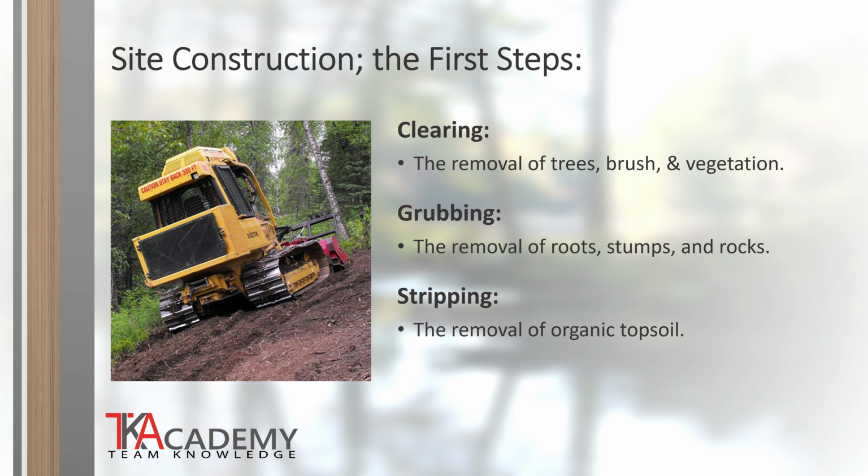The topsoil is where the nutrients are that plants need to thrive, and this material should not go to waste. At the end of the project, the topsoil is spread across the final grade before the plantings are installed. With the vegetation removed and the topsoil stripped off and stockpiled on the site for later use, the site is now down to the subgrade level. This is the level at which grading operations should be conducted.